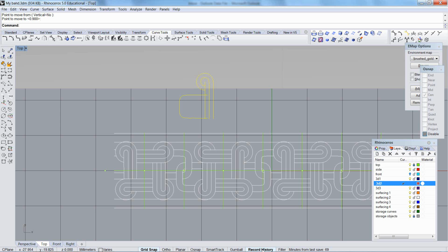It's important that this copy is done inside of Rhino. This is not Control-C, Control-V, where you copy it out to the Windows clipboard and then bring it back. This is where you actually copy the geometry within Rhino. It's the only way you can copy with history. The outside of Windows option will not retain history because obviously once you've copied it out of Rhino, it's left Rhino's memory and is no longer capable of holding history.